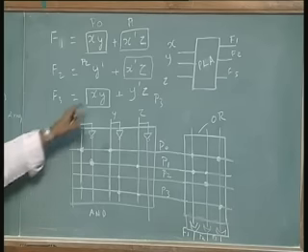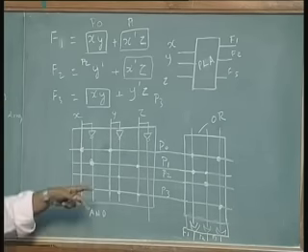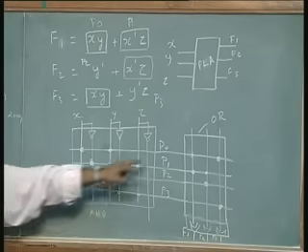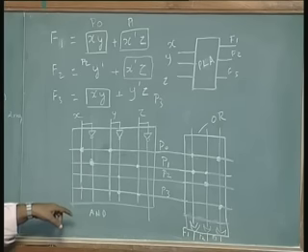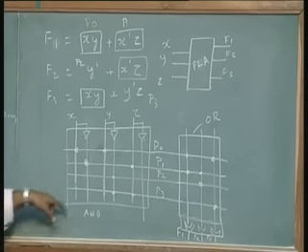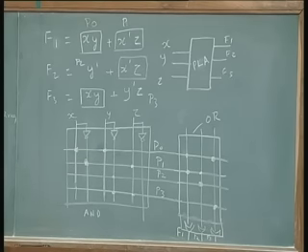And the fact that we have simplified such that common terms are available between different F1, F2, F3 functions, I can reduce the number of product terms I need to generate. That is the trick in programmable array logic design, programmable logic array design. You simplify such that as few product terms as possible are needed totally, not for individual functions. That is the only thing.